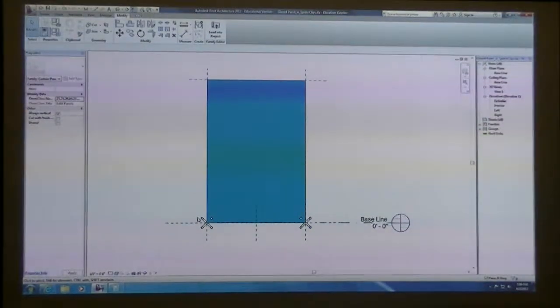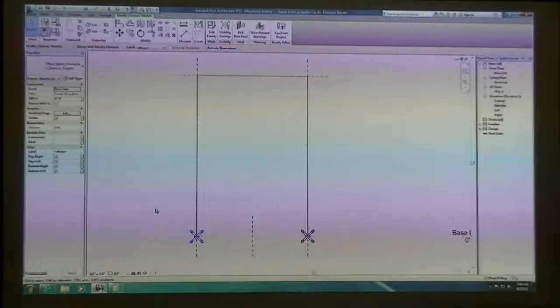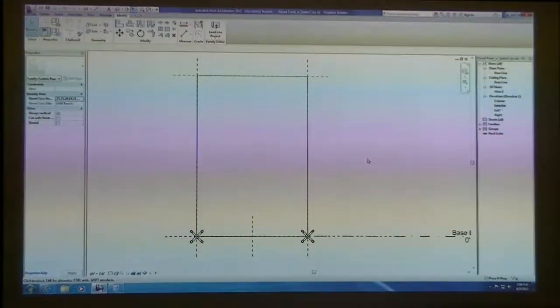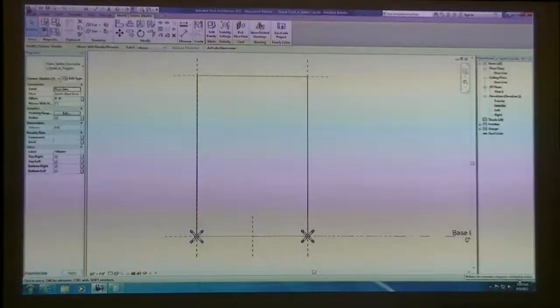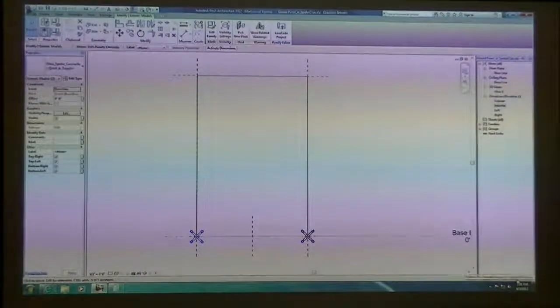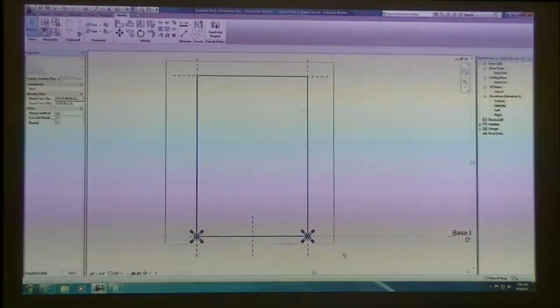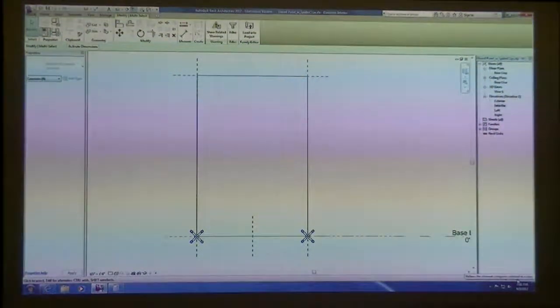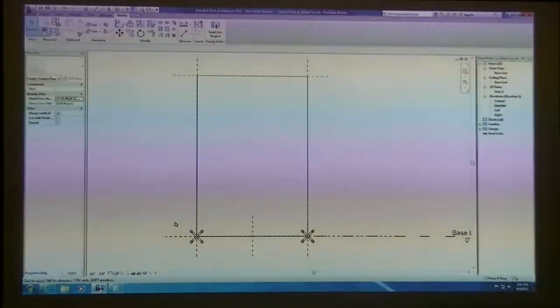So now let me go to the interior view. There we go. Look at your elevation in the interior view. On the left side, you should be able to select, and down at the very bottom it'll tell you that you've selected 2 instances of something. That's how you can see if you've selected only 1 or 2 or multiple items: the little filter icon and the colon down at the bottom right, and then the numbers. If you select more than one item, it gives you a count of what you've selected. So I can identify that that's the spot where I've modeled both of these instances.